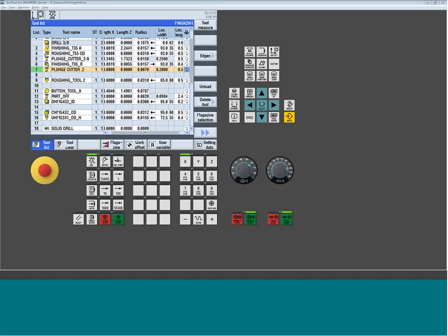Now, it doesn't necessarily know it's going to be stock at that point, so it's going to be up to you to order the shapes, because when you first bring in a DXF, you're just going to have a default program created with a couple shapes. But yes, you can have DXFs for the irregular stock.